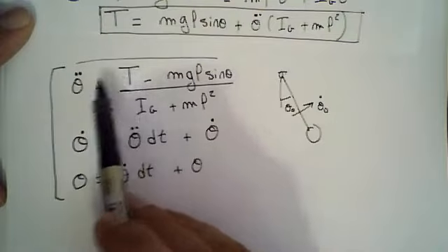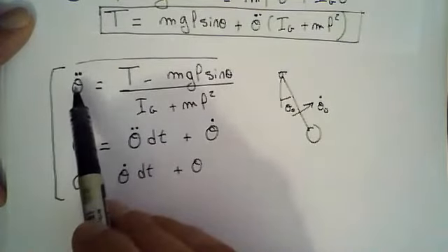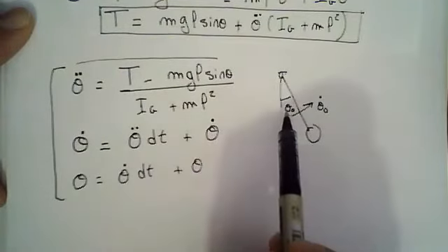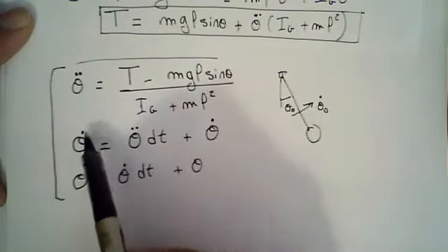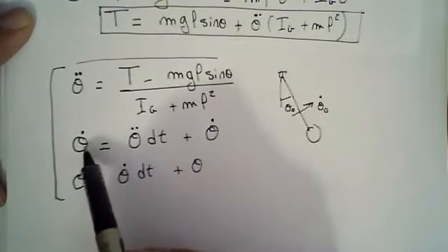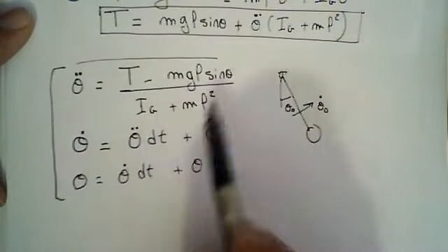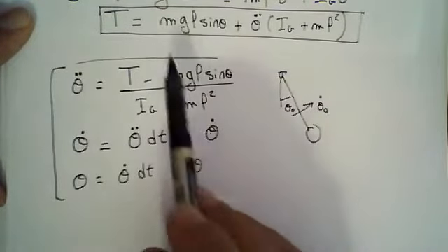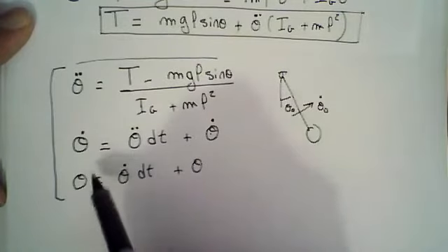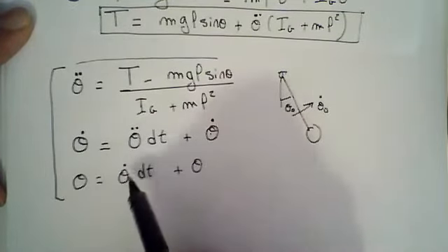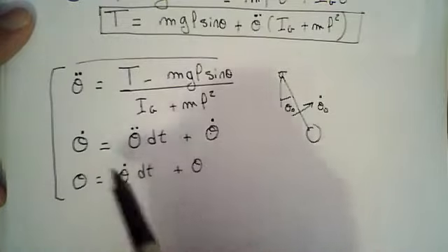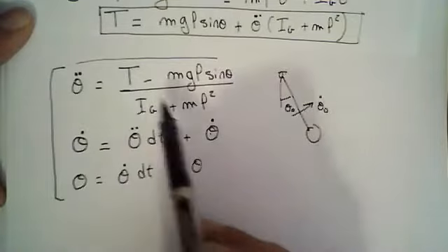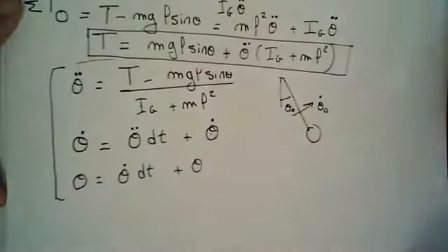And whatever torque I have as a function of time, I can solve for my angular acceleration based on theta 0, right? So I can obtain this theta double dot. Then I can jump one step and find my theta prime: whatever value I have here multiplied by dt, then add my previous velocity. And then I can find my position by integrating this numerically also. If you continue doing that, you will basically solve for theta as a function of time.